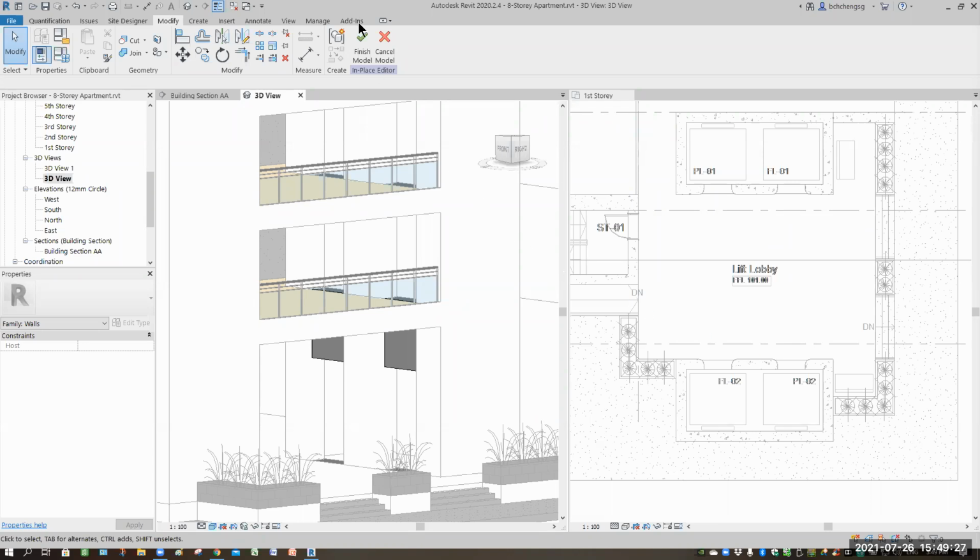So don't quit this thing yet, because now it is model in place. If you don't build it as a family, that means it cannot be recycled and used. In other words, it can only be used once. It's not transferable. So if you want to make this transferable, this is a step that I missed out last week. Ready? If okay, then I will show you.